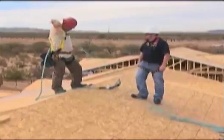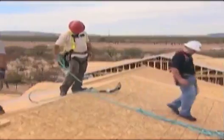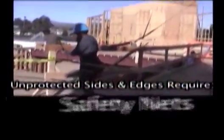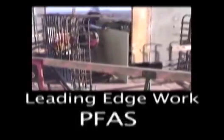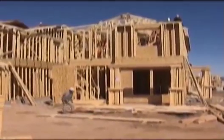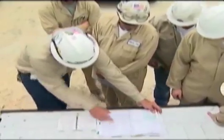Areas and/or activities where fall protection is needed and the type of protection required includes, but is not limited to, unprotected sides and edges require the use of guardrail, safety net, or a personal fall arrest system, PFAS. Leading edge work requires the use of guardrail, safety net, or PFAS. When it is infeasible to use fall protection, or it creates a greater hazard to use these systems, an employer may develop and implement a fall protection plan.